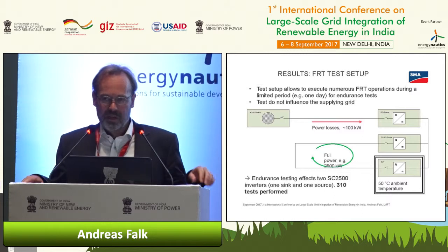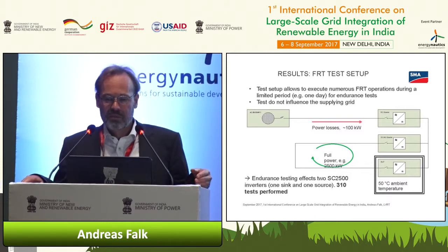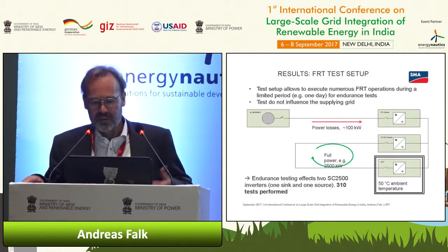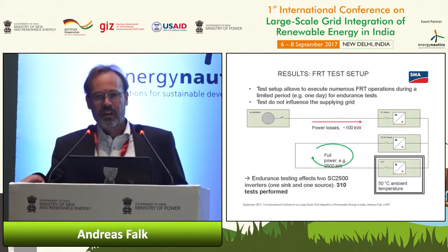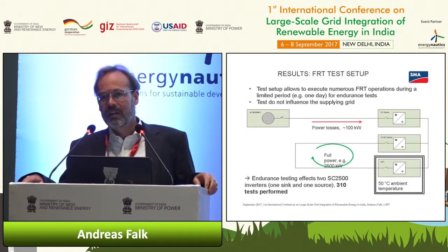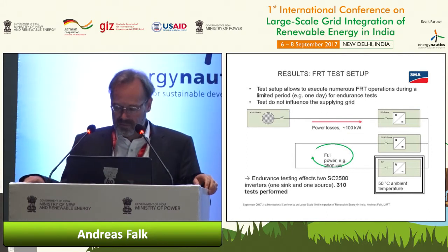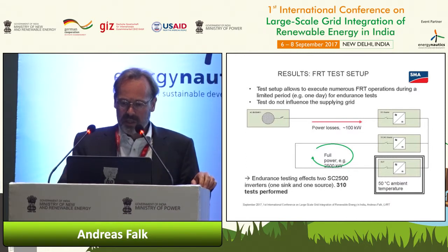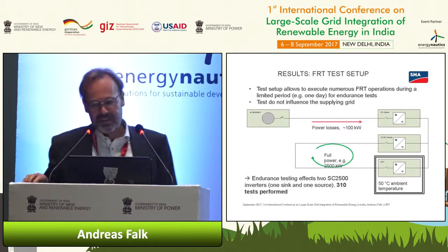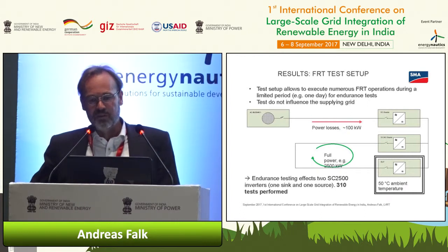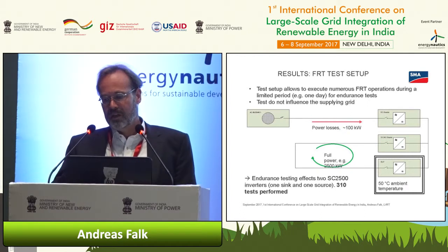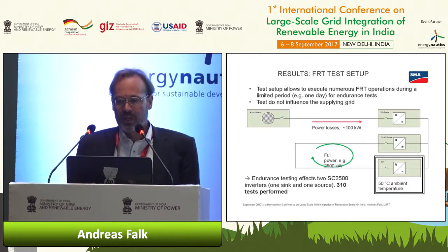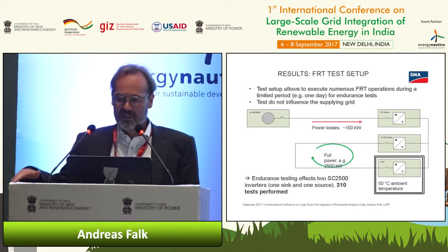And when you have STATCOM devices, they can react as fault ride through sources in most of the cases, but not in case the voltage dip is too deep. And what we can tune here in our test facility too is we can raise the DC voltage during fault ride through until nominal DC voltage.